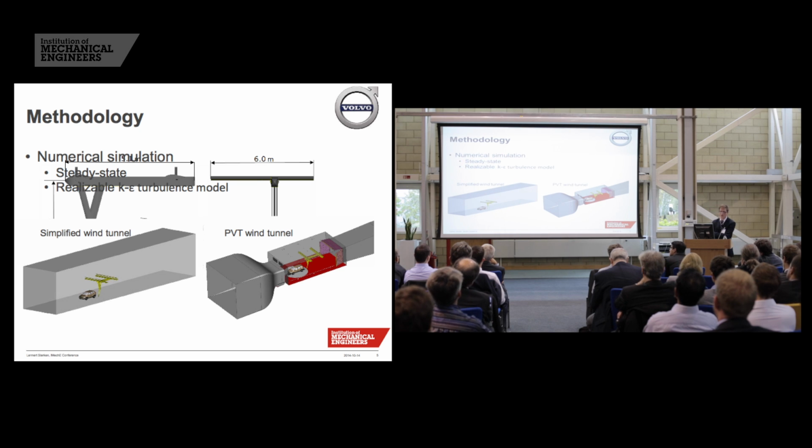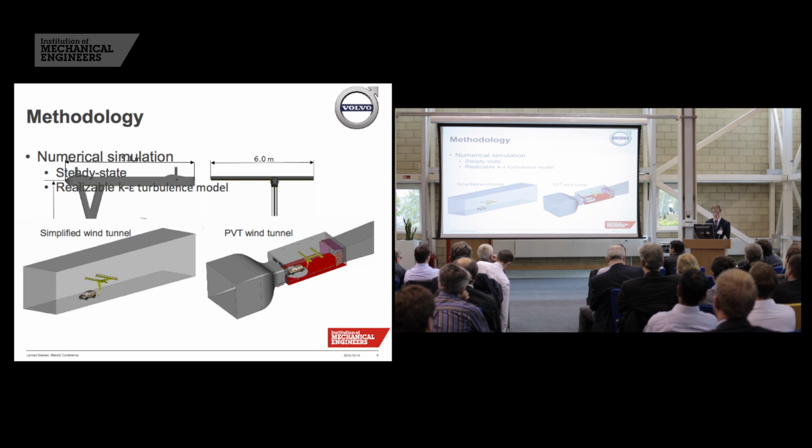During my numerical simulations, I simply used steady-state simulations with a realizable k-epsilon turbulence model, because it's our default procedure and it's relatively fast to investigate whether there are any flow structure differences. And I used two wind tunnel approaches.